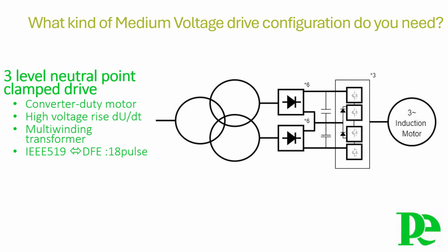This kind of drive can be fitted with an active front end to recover energy in advanced applications like rolling mills, test stands and downhill conveyors.